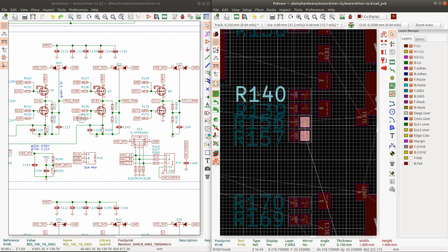So if you select some pad, you can actually move that pad. And what is the purpose of that? Like, if I need to move the pads, then I should be doing that through the component library. So I should be actually updating the footprint in the footprint library and then assigning that footprint to the component. So the footprints should not be modifiable on the PCB.